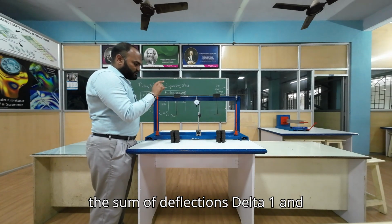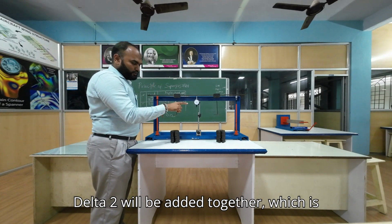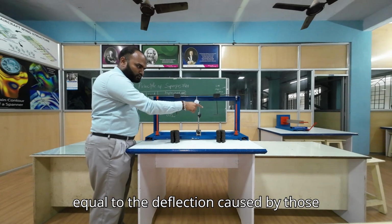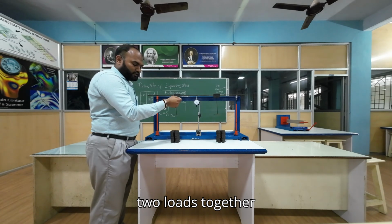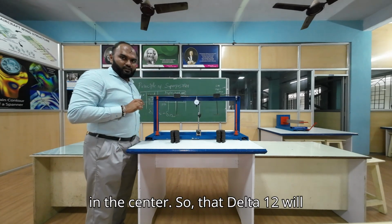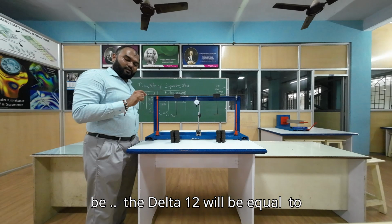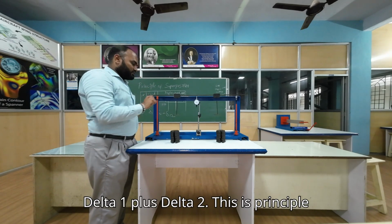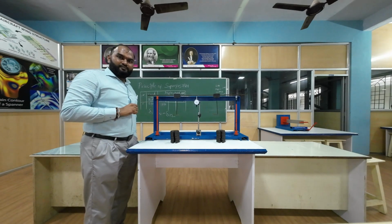So the sum of deflections delta 1 and delta 2 added together is equal to the deflection caused by those 2 loads together in the center. So delta 1, 2 will be equal to delta 1 plus delta 2. This is the principle of superposition.